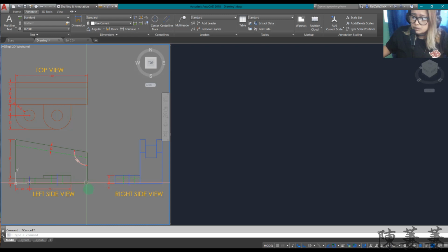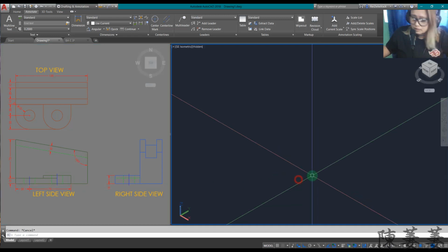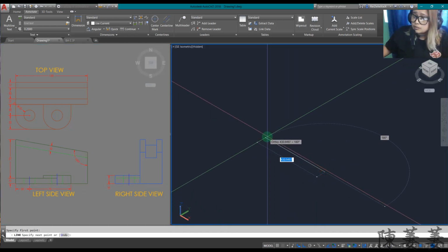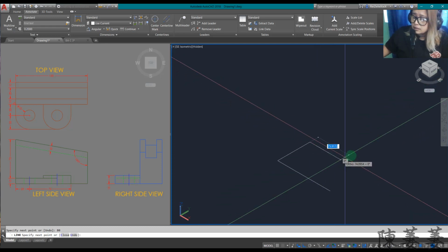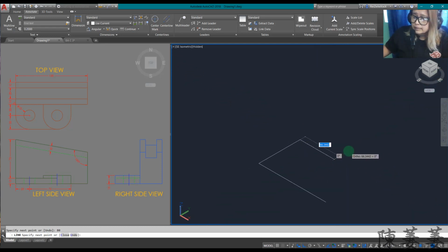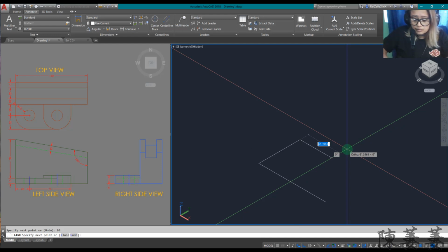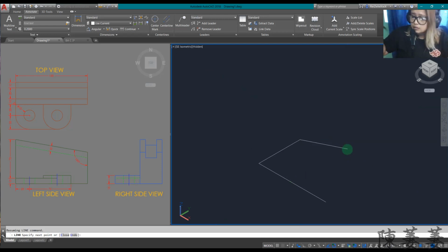we're going to start from this point, length 130. The height is 80. Then, using that angle, so shift, the less than sign, -10, or again, angle sign -10.